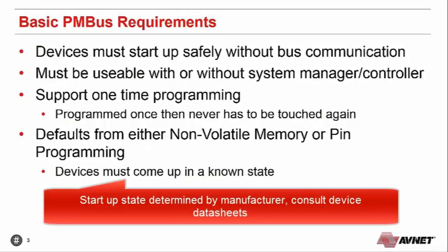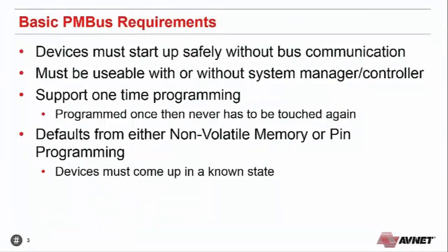Depending on the device, depending on the manufacturer, this is not always universal. Some parts will come up to a pre-programmed output voltage without external programming. Some have external pins that you program the initial voltage with. So it's important to look specifically at the device you're planning on using and then design accordingly.